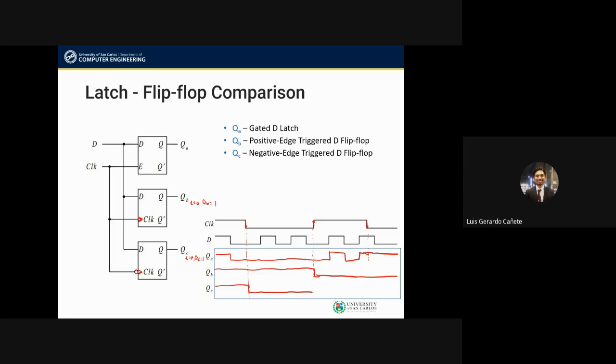We have no other falling edge, so we wait until we get to here. So now that we have the falling edge, we look at D, and D is 1 here right before the falling edge, so we have that logic 1 here, and then that is maintained as such. Okay? Okay, so this is how edge-triggered flip-flops work, right?